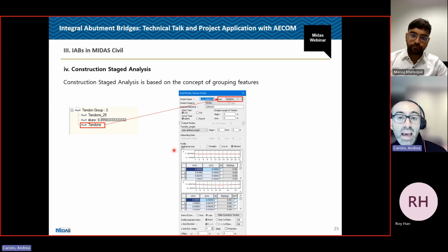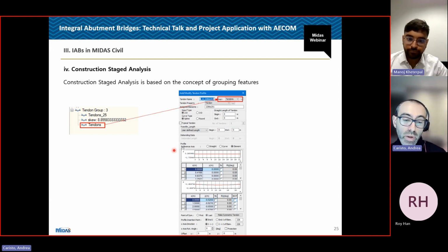Or it might be that they don't have the end block, that they're limited as to the areas where you can place it. So for pre-tension beams, I highly recommend that you talk to your prefabricator, really, and agree with them at the start of the project how to place your tendons.